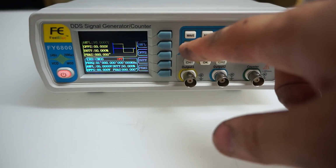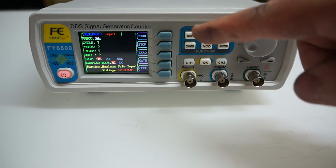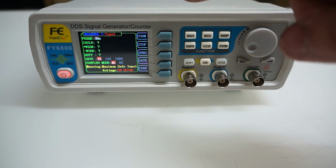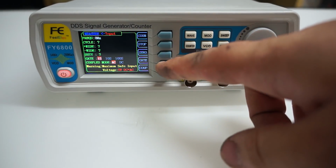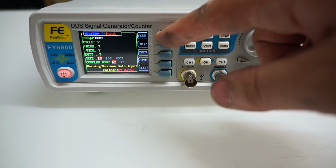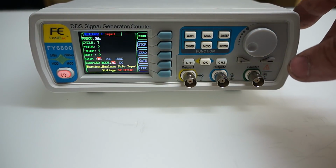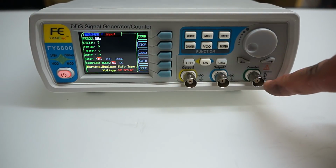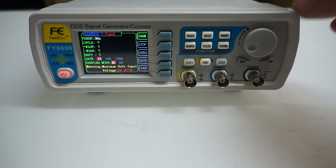On the next button we got the counter. It's this one. It's suggested to put in a maximum of 5 volts. It goes up to 100 megahertz and it shows the frequency, the cycle, the rise and fall time, duty cycle. You can change the gate, obviously, and the coupling. And if we hit count, it does counting. As easy as that. The maximum input voltage on the counter input is also 20 volts, so you shouldn't exceed that.